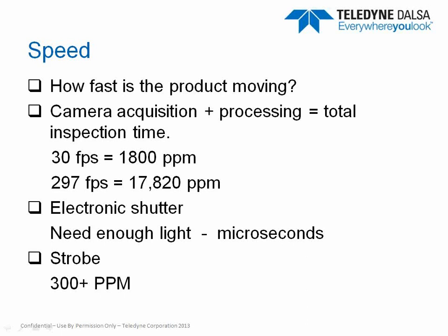So the new LED technology, you can take this little guy and pump up 4 amps of current, which will make the LED really bright, but for a very short period of time. You can't run 4 amps constantly, or you'll see the LED pop. So again, think of all the combinations and then the speed that you need in addition to that.